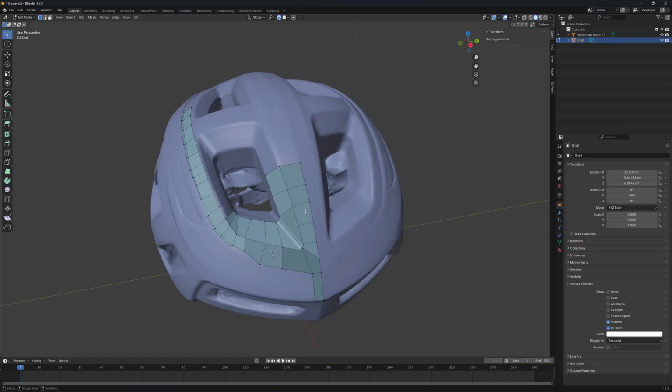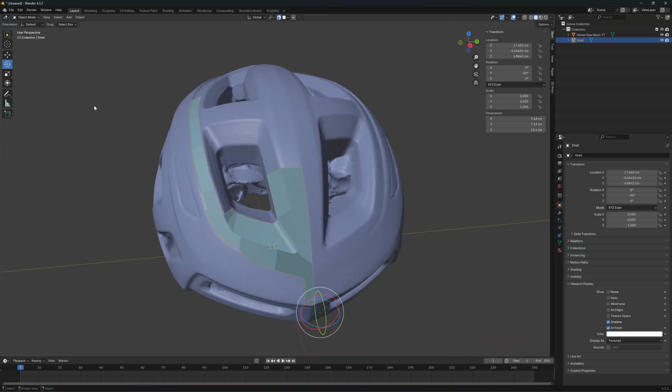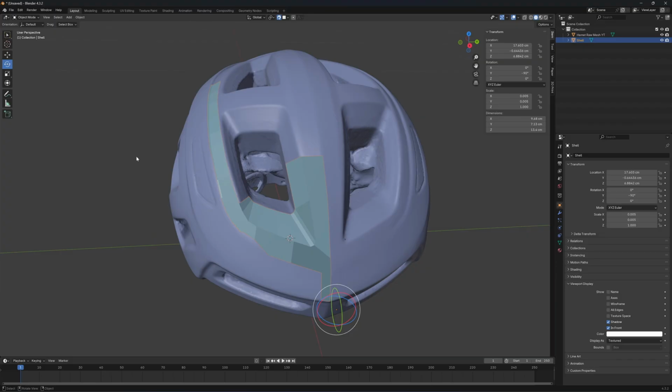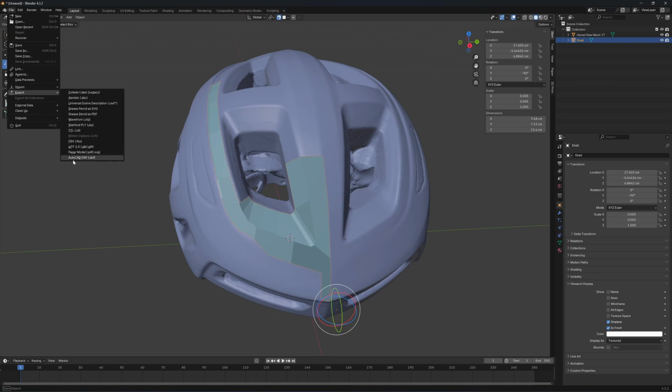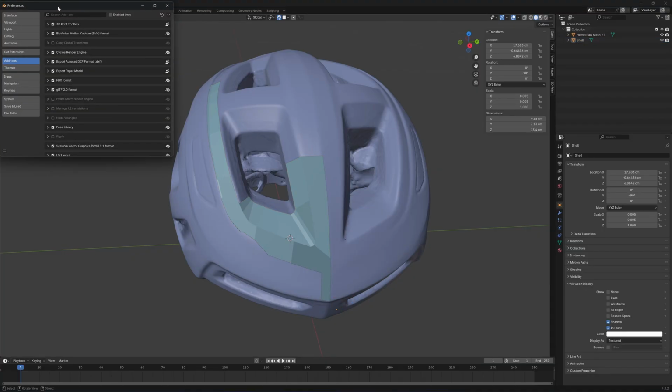Okay, now I'm done. I will show you how to export this back to the object mode, to export the 3D lines. I click on Files, Export, and there will be a tool called AutoCAD DXF. Before you can see this function, you need to add the add-on. Click on Edit Preference, Add-on, and then you go to, I think it's here. Yeah, here. Export AutoCAD DXF format.